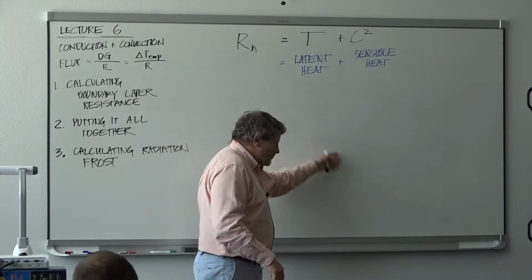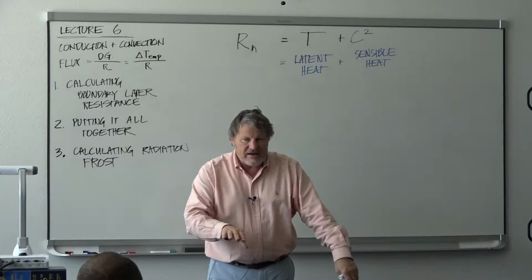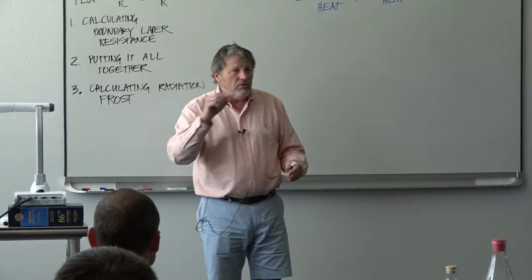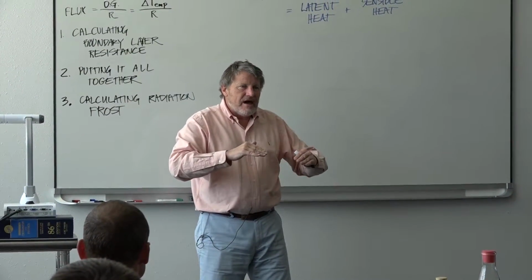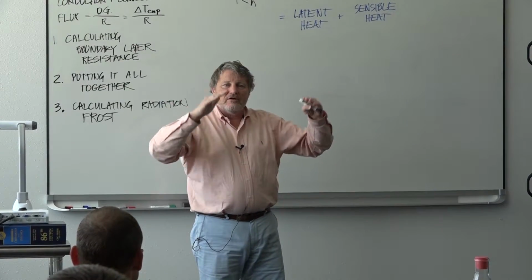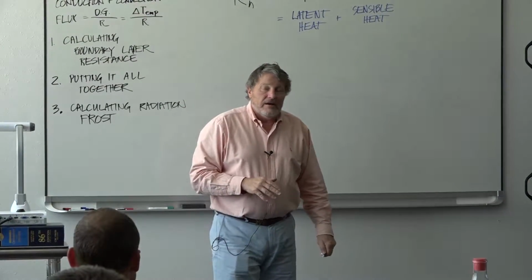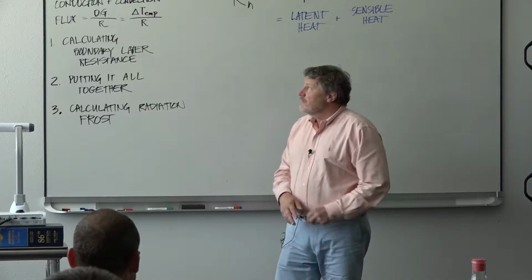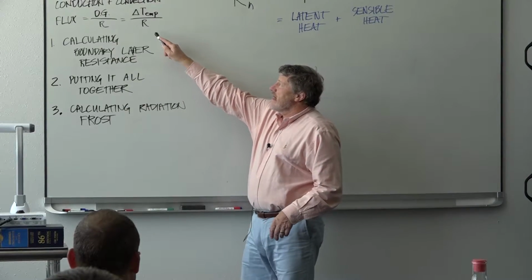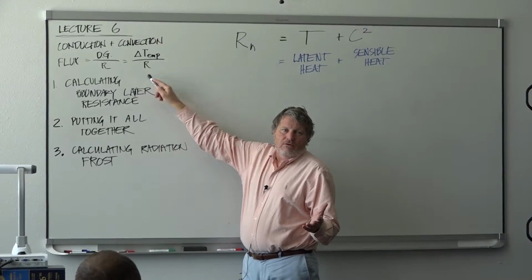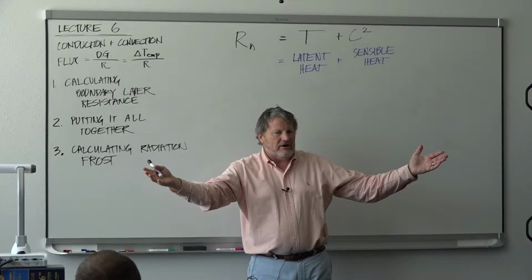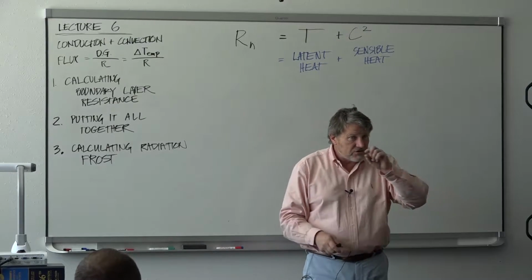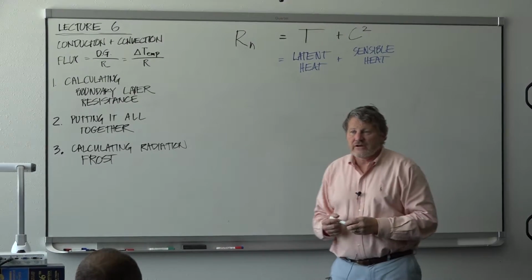This board has that, our skin has that, and that dead air is just like a thermal pane window, a tiny layer that resists the movement of heat. And if that layer was gone completely and the resistance approached zero, things would immediately equilibrate with the air. But they never do immediately equilibrate because of this little resistance layer.